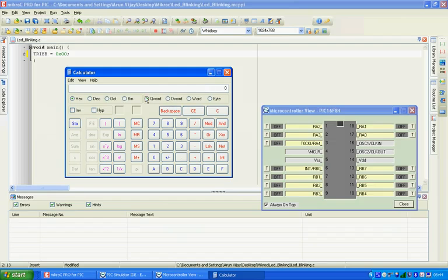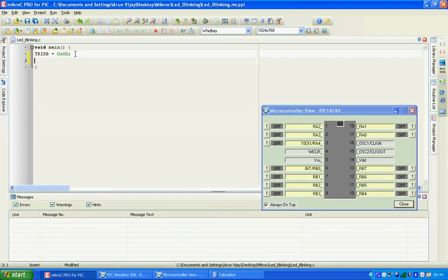Now, a PIC doesn't have an operating system. Something has to tell the code to run again and again. So inside most programs you will see an ever-running loop. In this case it's going to be while(1). This loop will run forever. When the code starts running, first the PIC executes TRISB equal to 0x00. It will see 0x00, so it makes port B output, and then it will come to while(1). The code inside this part will be running forever.